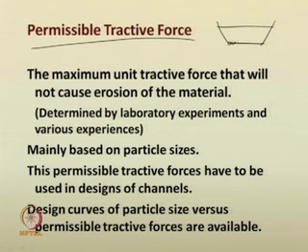The particles on the bed as well as the sides of the channel have a tendency to get eroded, because water is flowing along, it has its own gravity force, and various aspects can cause erosion of the materials. So, the maximum unit tractive force that will not cause much erosion of the particles from the bed or from the sides is called the permissible tractive force.